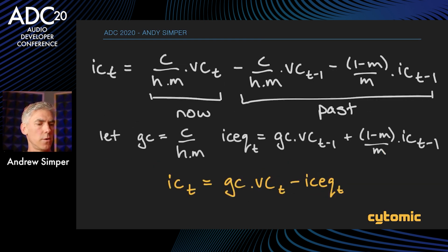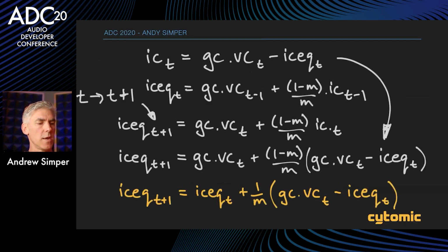All right, so we need to update our state as well, based on the solution to the linearized set of equations. Then we need to do that plus-equals bit to actually add on to the state. And notice this negative term, and that just makes things nicer. In a lot of the SPICE literature, they will not have a negative here, they'll have a positive, but this is better for circuit modeling, to do with the plus-equals side of things, which makes things look a bit nicer.